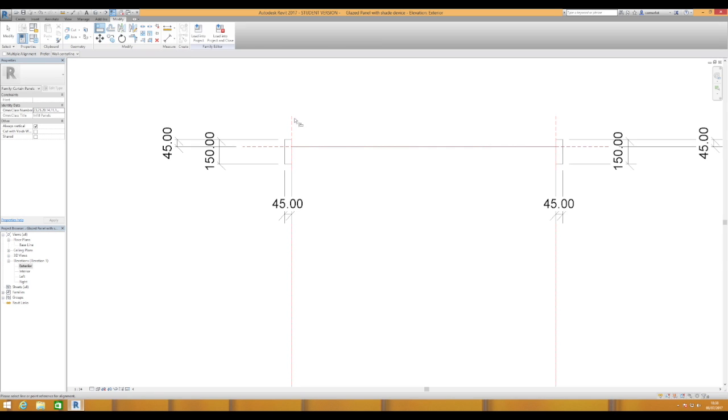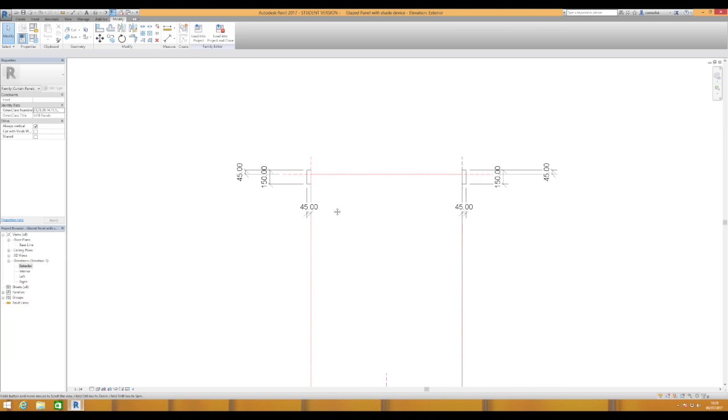Now I click that reference plane, it's the bit that's in the right place first, and then if I hover and wait till the extrusion edge is selected, I can align that. While they're aligned, nothing moved because it was already in the right place, but I'm using the align tool so that I can get this padlock up. And if I click the padlock now, that is aligned to that reference plane. So there's our next little bit in.